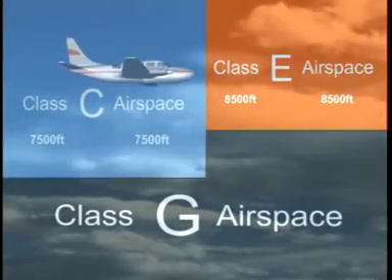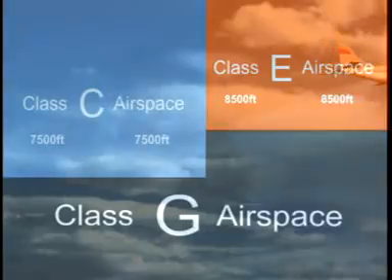We've just left Canberra's Class C airspace and we're now in Class E airspace. As an IFR aircraft, leaving Class C we already have a clearance into the Class E. We need to be aware that we'll be separated from other IFR aircraft and we'll only get traffic information on known VFR aircraft on a workload permitting basis. We need to fly at proper hemispherical levels and maintain a good lookout.